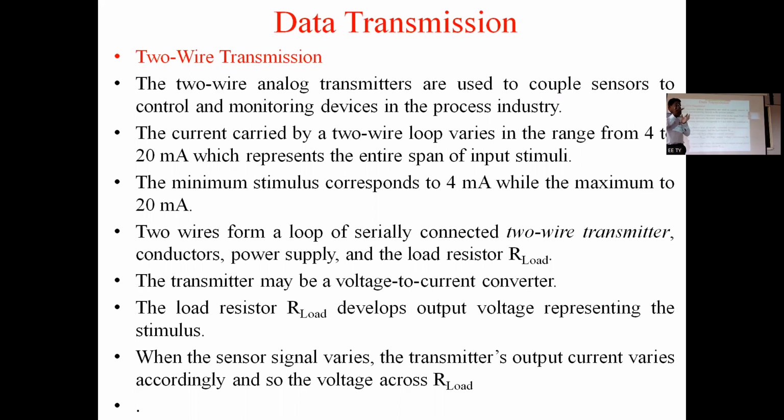So direct digital is connected to the microcomputer, or some analog to digital converter can be interfaced between multiplexer and microcontroller or computer. बरोबर? After that, computer काय करतं? It will process or monitor that data. बरोबर ना? It will monitor that data, and give command to the peripheral signal or actuator to control that situation.